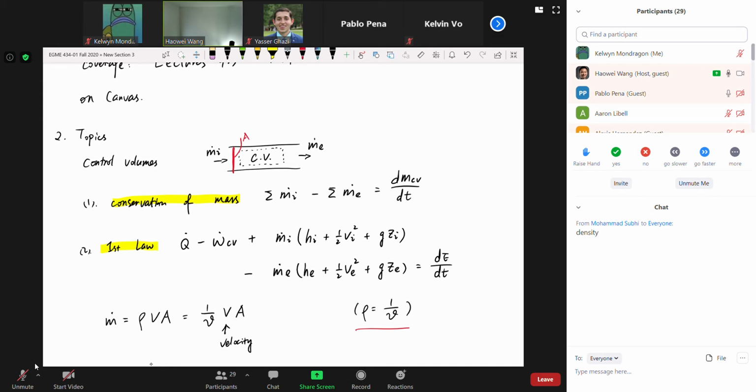How do you plan to look for nu if it is a mixture? What's it called again? It's not purity, it's called quality. So one minus quality, you add. Yes, very good, this is the equation. If it is a mixture, you have to come to this equation to look for the corresponding nu. X is called quality, not purity.